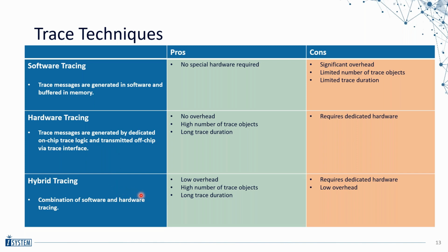But they don't have the full hardware trace capability, but they might have a compromise. So they might have something like on the RH850 that's called software trace. The way that works is you execute a dedicated instruction, and you have to add a little bit of instrumentation to execute that instruction, but then for that instruction a hardware trace message is generated, right? So it's a compromise between software and hardware tracing, and that can be more skewed towards software tracing, or it can also be closer to pure hardware tracing.